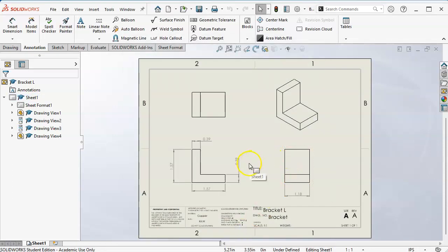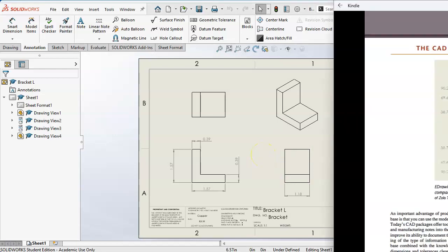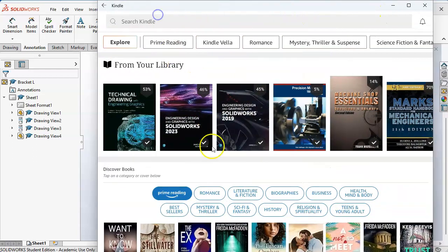then we are folding up the box to where this view is here as opposed to looking at it this way, and the top view is looking that way. All right, so minor differences. It comes back to what you're taught and what will be least confusing based on what you are taught in the way of the first angle. So in effect, a second and a fourth angle would just be repeats, and that's why you don't ever hear about those even coming up in discussion.